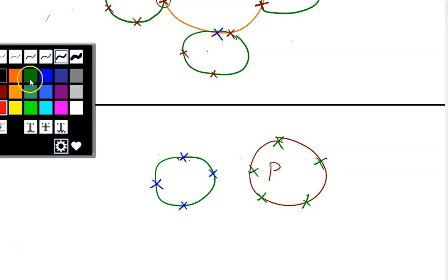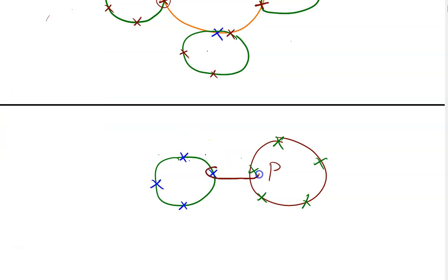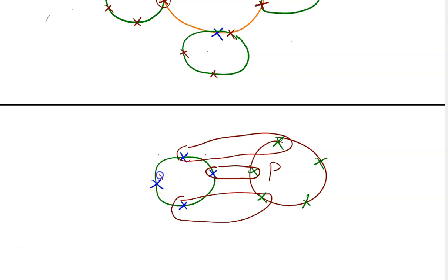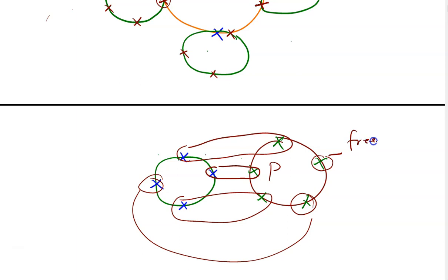If we are bonding these elements, this will bond with the first one, this will bond with this, this with this, then this one all the way bonding with this. So the phosphorus should have at least 8 electrons at the outermost shell. At this point, you see there was one free electron left in the phosphorus, and this electron is termed a free electron, thereby giving its name n-type semiconductor.